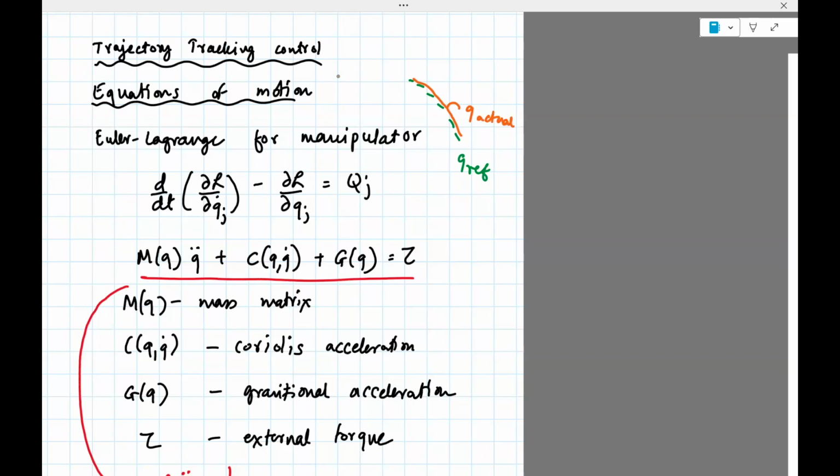So far what we have done is we have ignored the dynamics totally. We've always used MuJoCo forward, which doesn't do dynamics. So we need to use MuJoCo step, which I'll talk about. We've used mj_step in dynamics, but not for anything other than getting the dynamics. I'll show you how to do this control at the end, but really we will try to track a reference which we generated in the previous class.